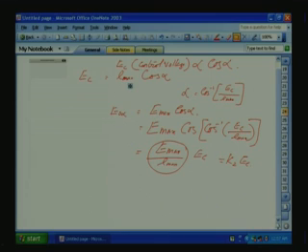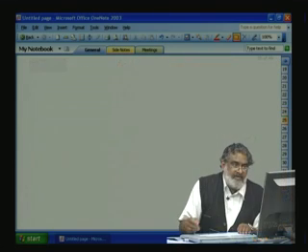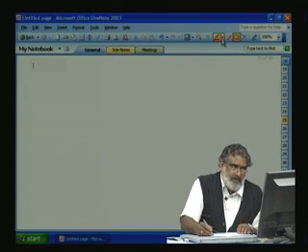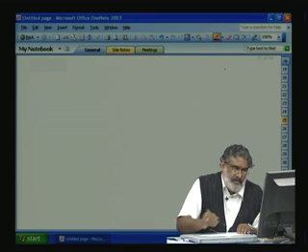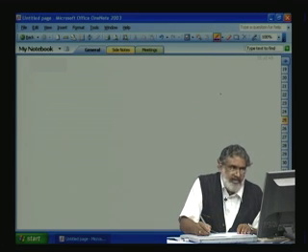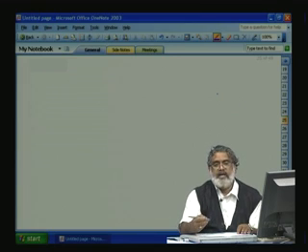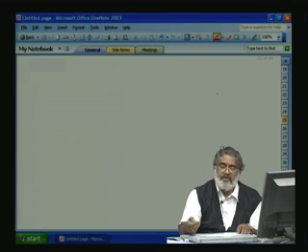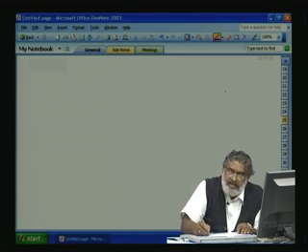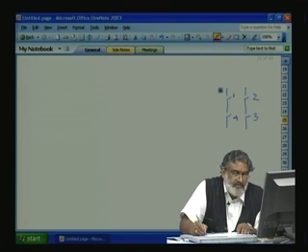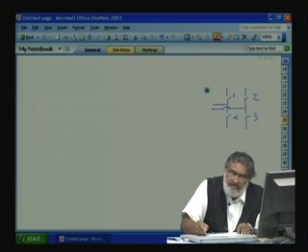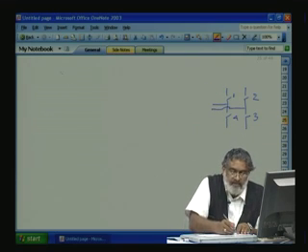So, let us see how it can be done. Again, we will take single phase only. For 3-phase, the corresponding reference sine waves 120 degrees apart have to be generated from the mains. Now, let us take a single phase control. I am representing the switches like this. This is 1, 3 and 2, 4. This is our waveform. Now, let us draw the waveforms.